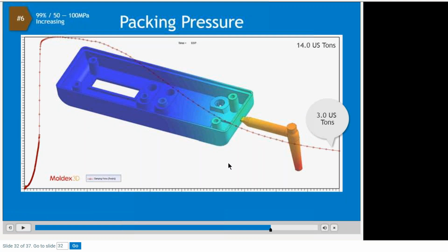If you have the pressure monitoring capabilities on your molding machine, take a look at your in-cavity pressure sensors. If you see that the pressure stays up at the end of packing, never goes down to 0, what it basically means is you're entrapping pressure in the cavity, basically overpacking material, trapping pressure, which can cause high residual molded-in compressive stress, and it could also cause some ejection problems.